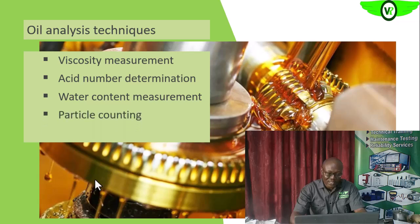We are also going to look at particle counting. It's another analysis technique, and that gives us the concentration of the wear particles per unit volume of the lube oil. So we have what is acceptable, and if it goes beyond certain limits, we know that will affect our engine. Spectroscopic analysis also is another form of the lube oil analysis that we will be looking at.